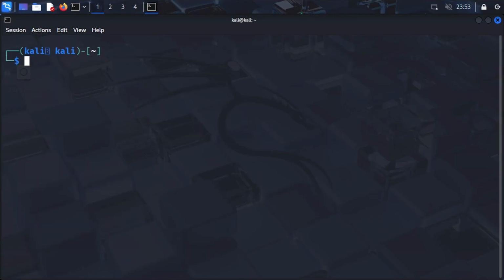Before we move on from here, I need to emphasize that active scanning of ICS networks is not necessarily safe. Only do active scanning with Nmap on an ICS network if you have permissions and if you're sure that it's going to be safe. Otherwise, try to do passive scanning or something else. But for this lab, we're going to be doing some active scanning because there's not really any risk of anything going wrong. So to scan both of these networks for potential ICS devices, we're going to use Nmap.